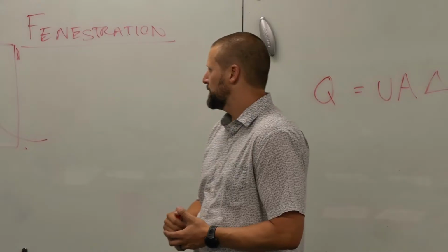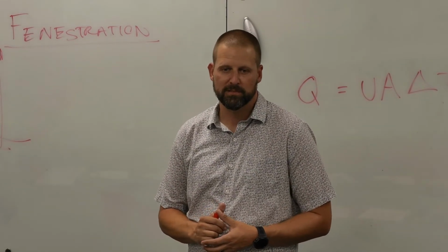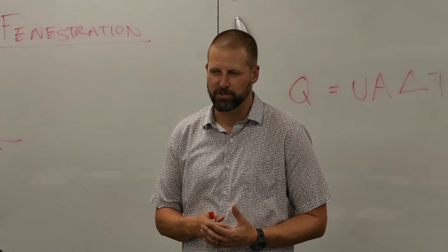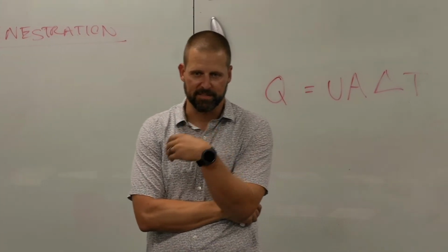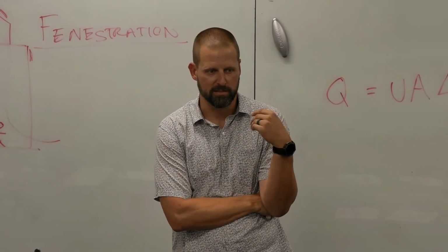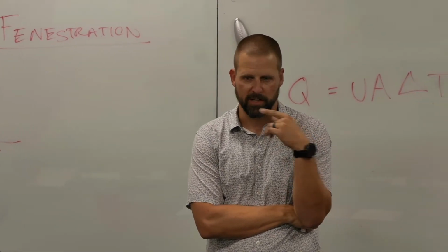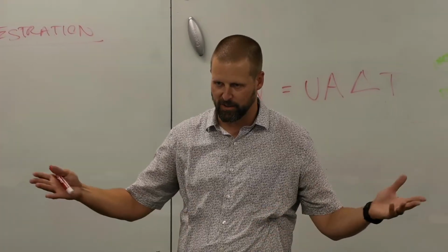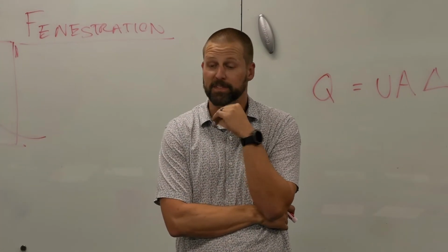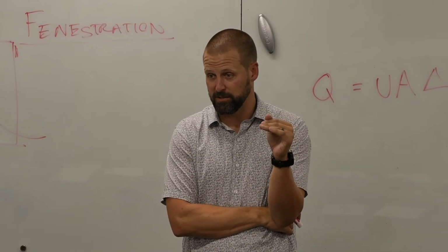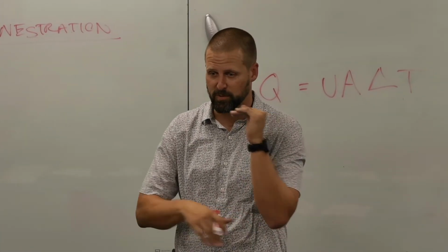This is a natural ventilation strategy. For certain areas, natural ventilation is not desirable. Commercial office spaces, that's not true. There's a good amount of commercial office spaces that have operable doors and windows. Continental has a lot of stuff that opens out into patios and cuts out air conditioning. Still, code requires mechanical units though, so don't let anybody VE air conditioning out of it, even if you can open a window.